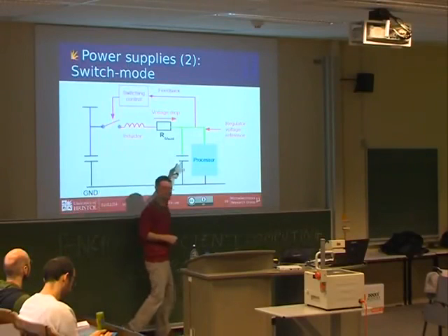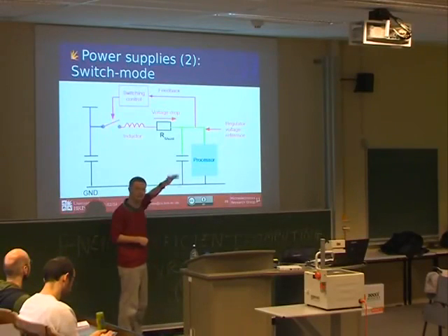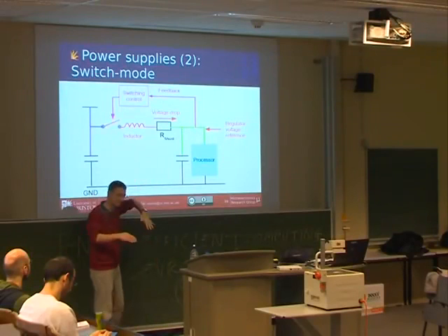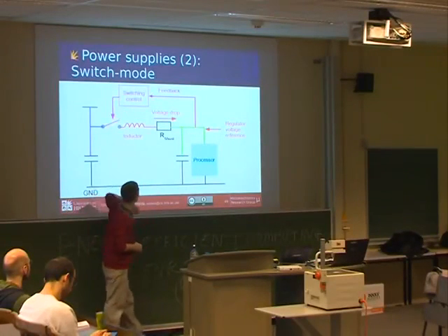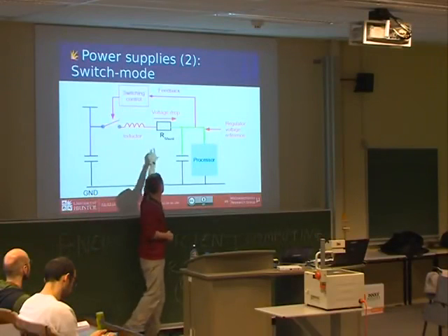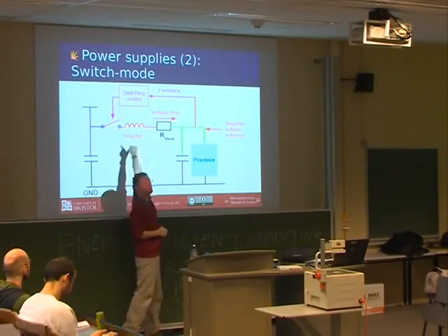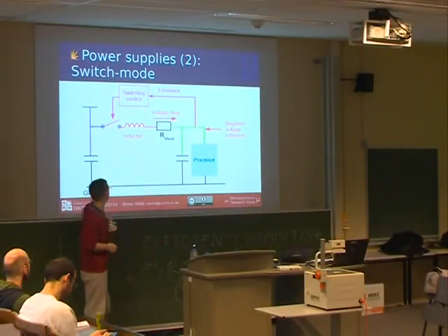And it looks at the output and says, do I need to connect the power supply again? If the voltage is too low, connect the power supply, if it's too high, it stops. So this thing goes up and down 20,000 times a second, and there's a measurement point where feedback comes in to decide whether to close the switch.